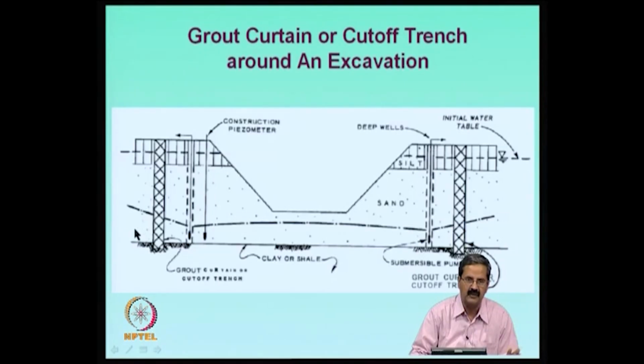The soil or aquifer is essentially a sandy system in which the permeability is going to be high. The moment you make this well point system, there is a tendency for the water to rush back so that the groundwater comes back to the original condition, but we do not want that. What we try to do is keep this area free of water, but at the same time intersect this flow line by putting in a curtain made of impermeable materials. It can be bentonite, a geomembrane, a cement slurry and so on.